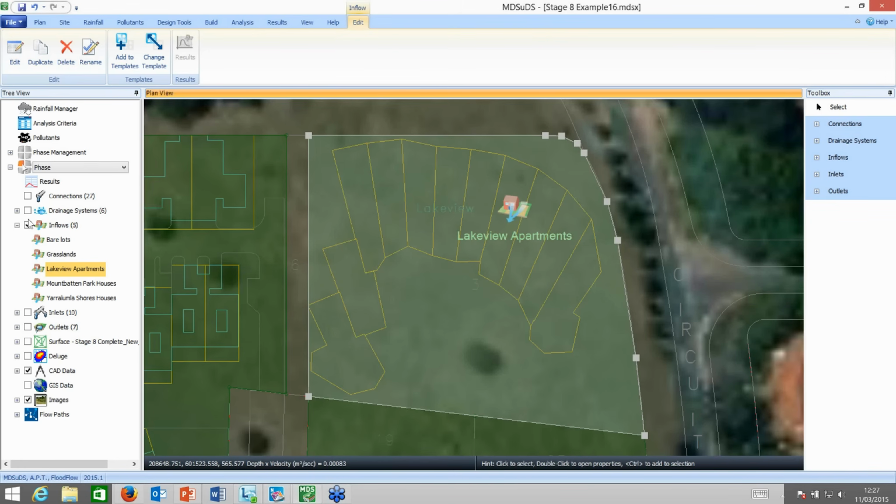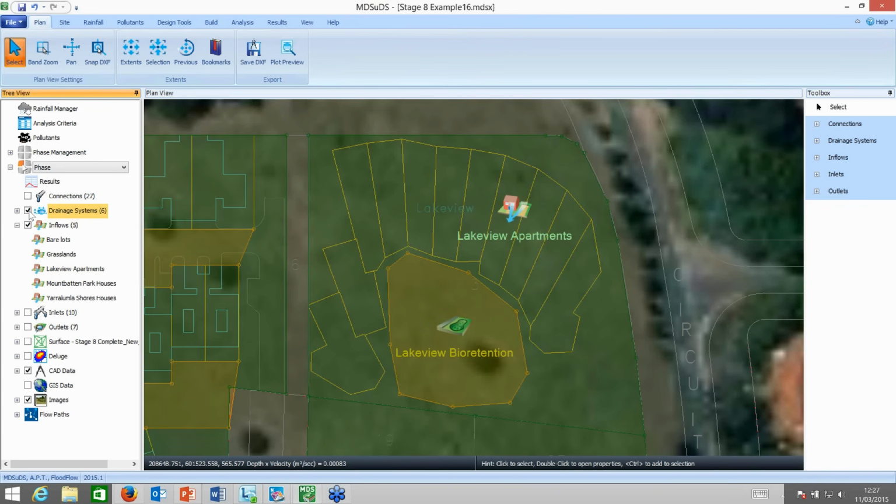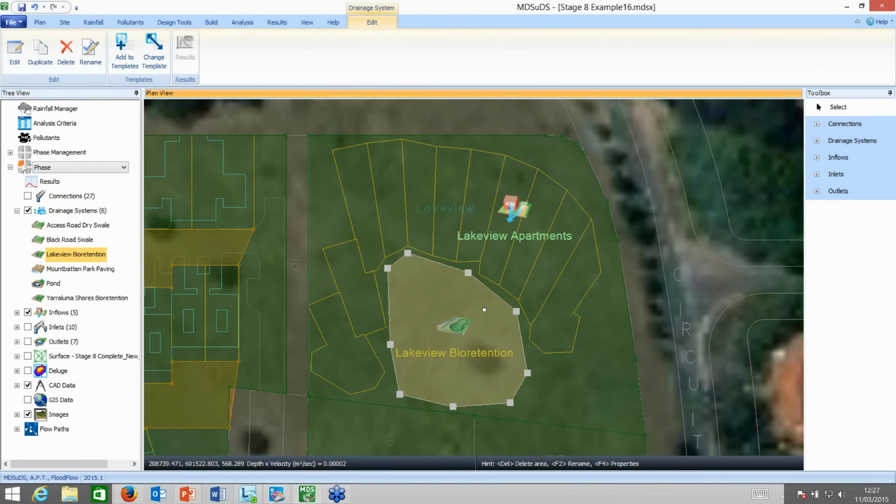Where's it going to? Well, I can now switch on the drainage system or the drainage systems. And this is showing you the extent, literally the footprint, of a bioretention area. Now it's flooding just a little bit down here. So my rationale is if we just massage the landscaping around and then create the pit here with infiltration layers, with filtration layers underneath and landscape it, we could fit that in here right at source and take account of that runoff with maybe some positive discharge flowing down to the next system as well. Let's see what this comprises of.